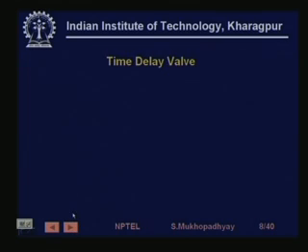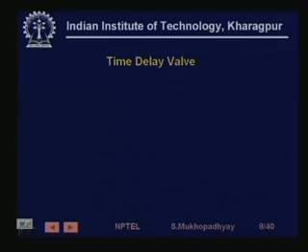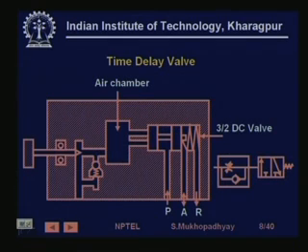Similarly, sometimes you want that for synchronization purposes. You would like that after you put an actuator, there are 3 valves that will actually move one after the other. So, if you have to realize this concept of one after the other, then you have to create gradually increasing time delays, after which these valves will be shifted. So, that is done. This is a typical construction.